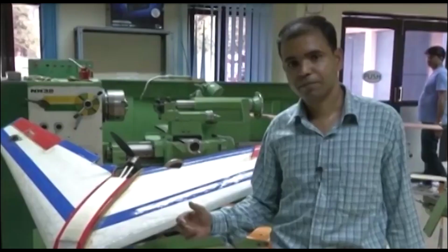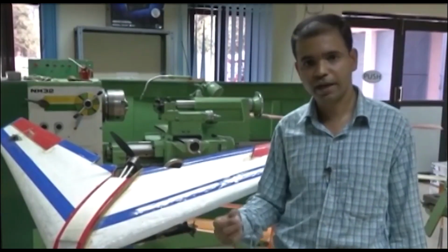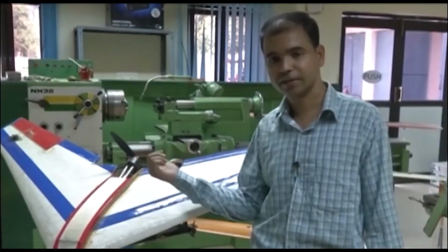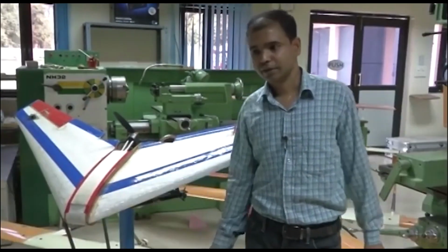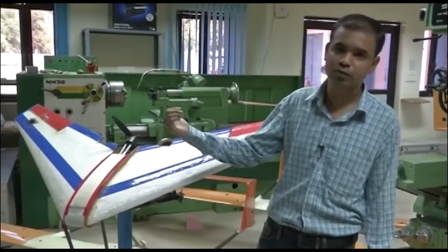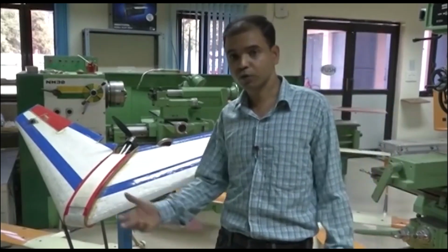As you already know, for an aircraft to be stable, our aerodynamic center must be behind the center of gravity. That we can achieve by adjusting the weight distribution. If our aircraft is unstable, it doesn't mean it cannot fly. It can fly by giving some suitable feedback into the control surfaces, like our body is unstable to move on a road, but we can move.